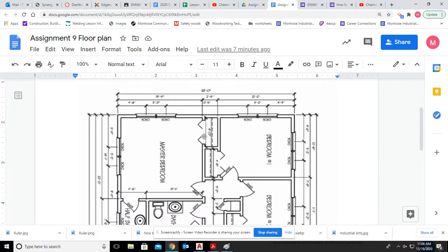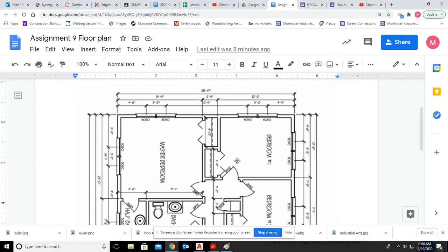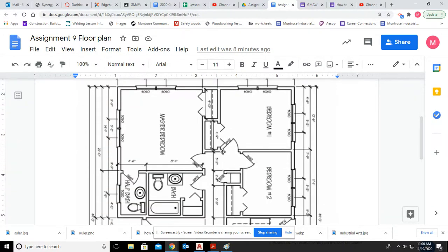This is 4 foot 9 wide for the closet, so I'd get a center point, or just measure 4 foot 9 over, and that'll be your closet area. And we can come back and add these doors. The one thing I actually add, if they don't have it, is this distance from the edge of the door back, so we don't really know 100% where this door is. They didn't include that dimension. So you can fudge some of these numbers, you can position that 2 foot 6 inch wide door, that 30 inch wide door, somewhere here. Now, what I normally do is I make sure that I have 6 inches from the edge of the door back to there, and vice versa.